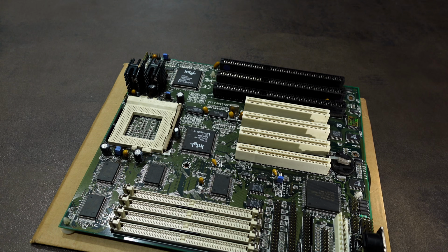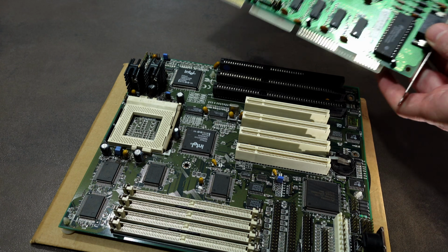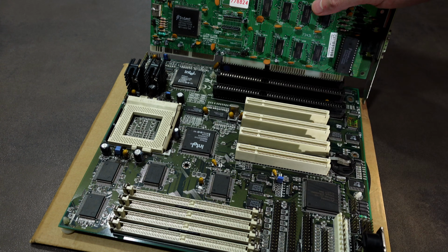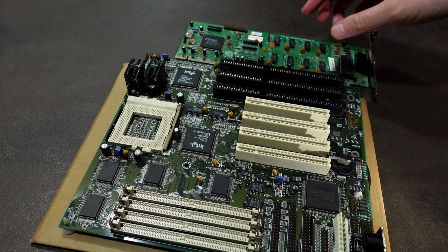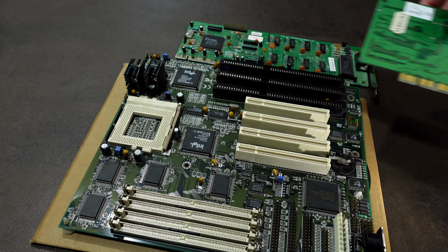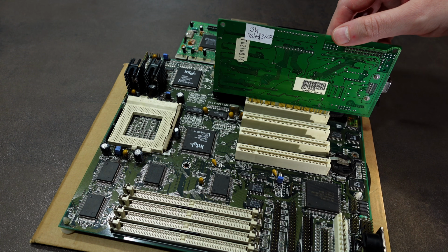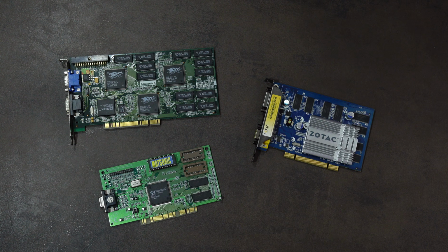However, if we go beyond the 486 CPUs and from socket 3 to socket 4, then these VLB cards are no longer an option. They just don't exist anymore on these newer boards, so that you can only opt for these shorter and slower ISA cards or get one of the plenty PCI cards which are significantly faster. So the decision is most likely to go for PCI in that case. Time to take a look at the differences among these PCI cards.